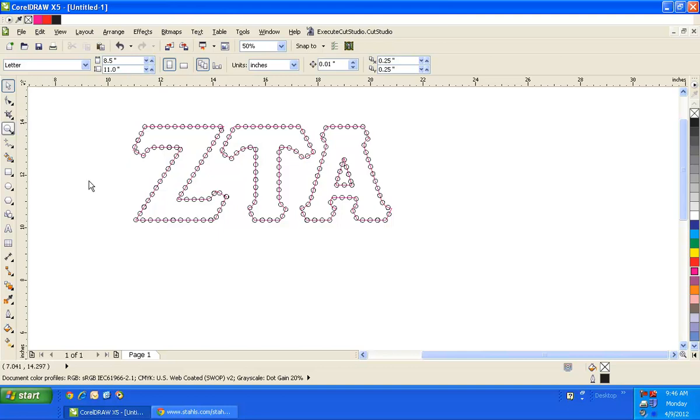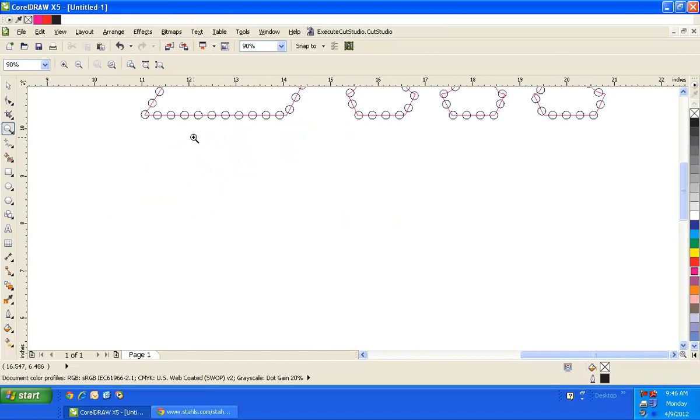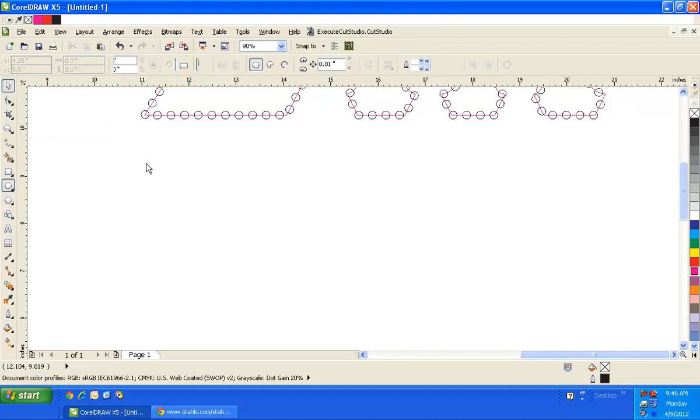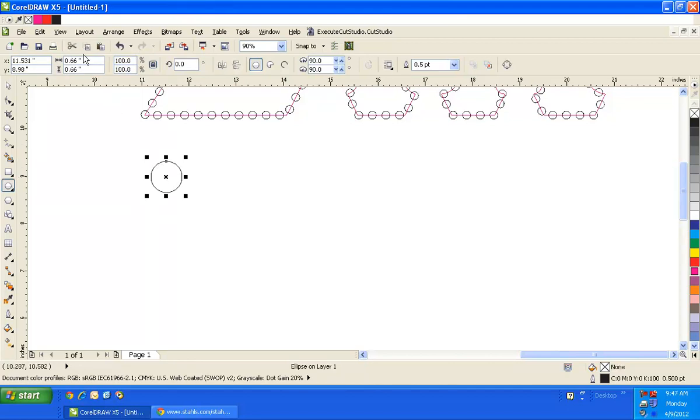start creating the fill. I'm just going to do this the easiest way that I feel. There may be easier ways out there, but this is the way that I feel is the easiest way to do it. So I'm just going to start another circle, hold my control key down, click and drag my mouse, and it will make a perfect circle. Let go of your mouse before your control key to make a perfect circle. And then I'm going to change my size, 4.3 mm, enter on my keyboard, and it converts it for me.